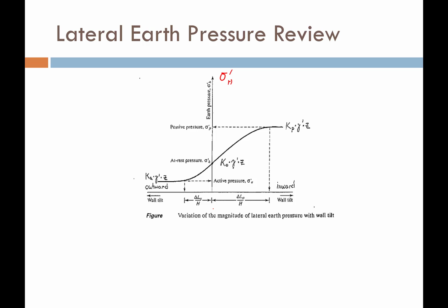In that instance, those supports are transmitting the force down to the soil, and they're pushing the soil, and the soil's shear strength is resisting that. So because something is pushing the soil, that would be a case of passive pressures. So hopefully that's a little more clear to you.